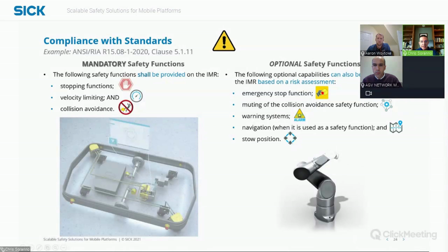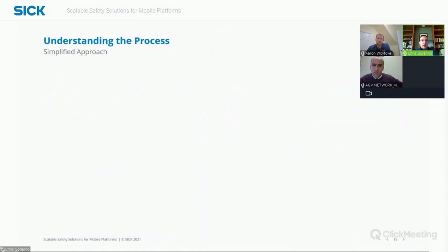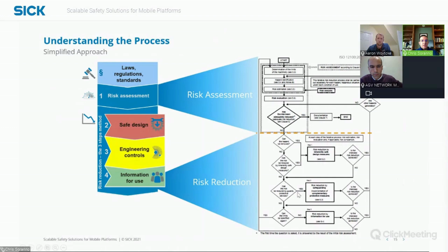It goes back to the idea of the risk assessment process in general, where often people would stop at step 2, say, okay, I'm at the performance level, I'm done, and not consider, are there other measures either required by standards, by regulation, or simply to reduce the risk to that ALARP concept, as low as reasonably practicable? Is it addition of signs and documentation and training and supervision, all those things that are admittedly harder for the supplier to implement, but definitely important for the end user to make sure those extra levels of risk reduction are